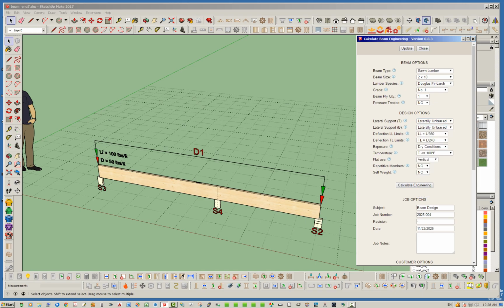And then you can override, in a sense, and set bracing at specific intermediate supports. And again, remember, at the outer supports, we're always braced laterally top and bottom. And just a reminder, when you set the blocking, you are specifying top and bottom bracing at that particular support.